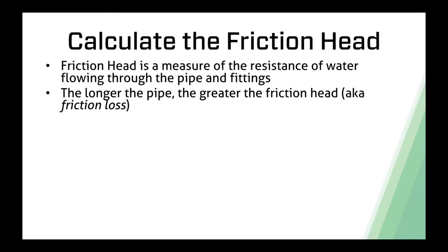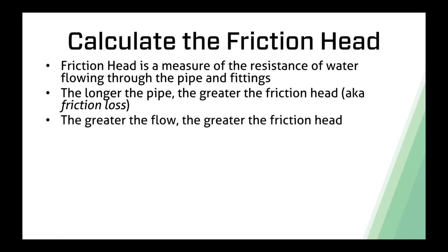When we were talking about static head, it didn't matter how long of a pipe you had. The only thing that mattered was the elevation difference. But when it comes to friction head, the more pipe that water has to interact with, the more frictional losses or frictional resistance will build up. Also, the faster you try to shove water through that pipe, the more friction head you're going to see.